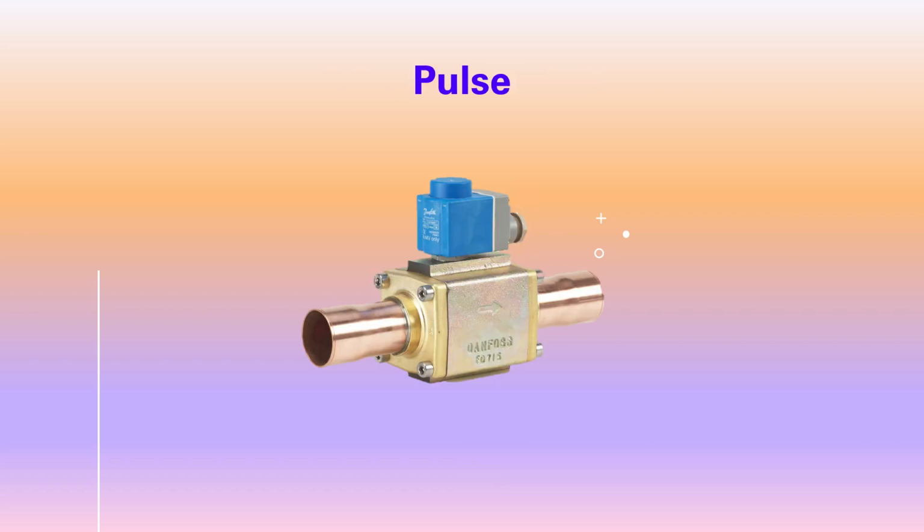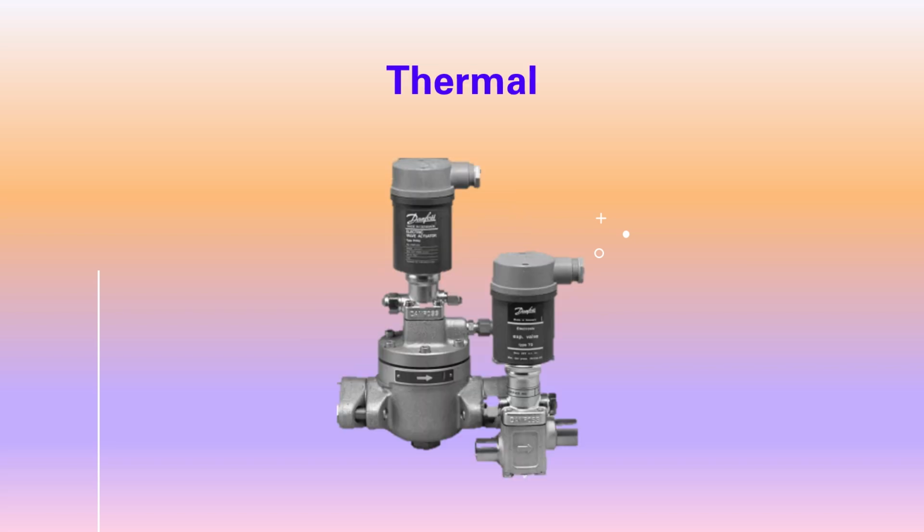Here you have a pulse valve, as the name implies. It pulses, and a piece of electronics reads the superheat at the end of the evaporator and opens and closes the valve to regulate the refrigerant entry. Here's an example of a thermal type valve, not used so much now, I don't think. The head is wax filled, it has a heating element in it and a temperature sensor in it, and the electronics pulse the heating element, and as the wax expands, it opens the valve and that regulates the refrigerant.